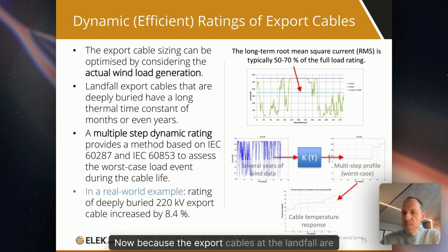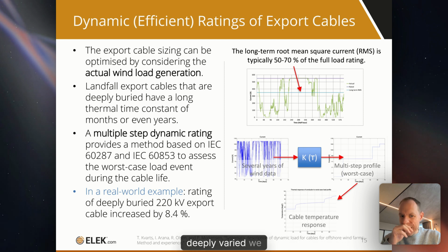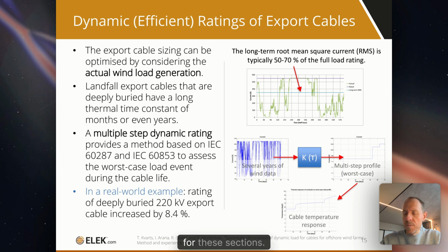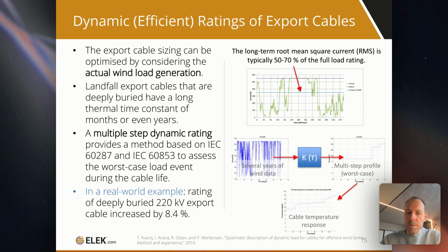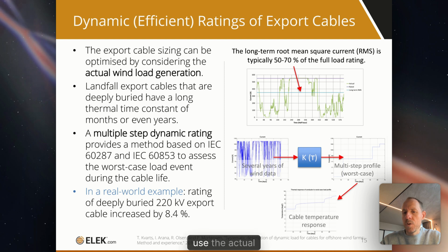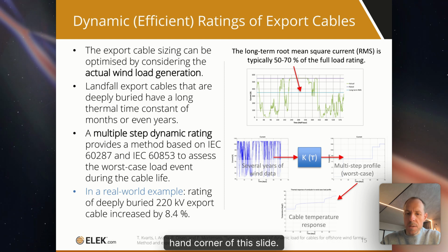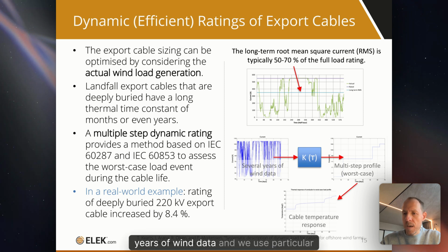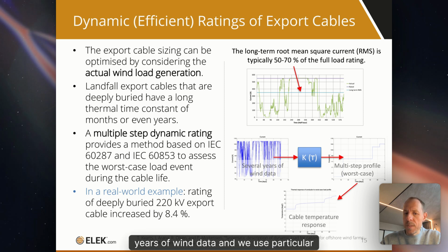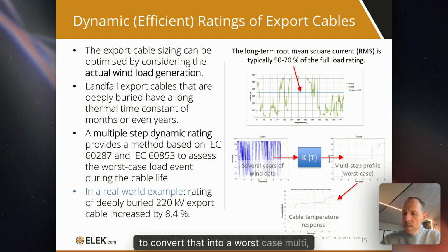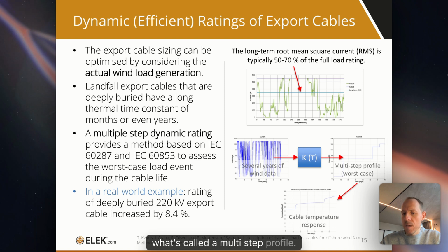Now, because the export cables at the landfall are deeply buried, we can take advantage of long thermal time constants for these sections, and we can use the actual load profile from the wind farm. You can see an example of that in the top right hand corner of the slide. We should use years of wind data, and we use particular conversion methods to convert that into a worst case what's called a multi-step profile.